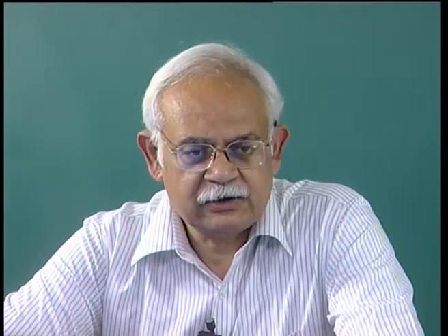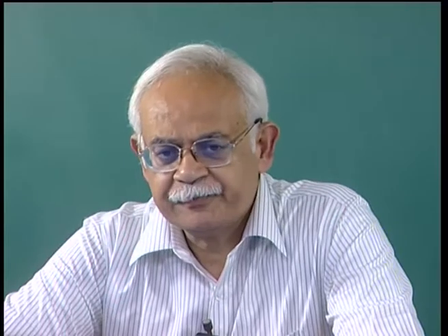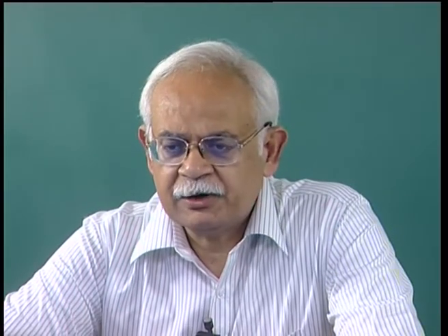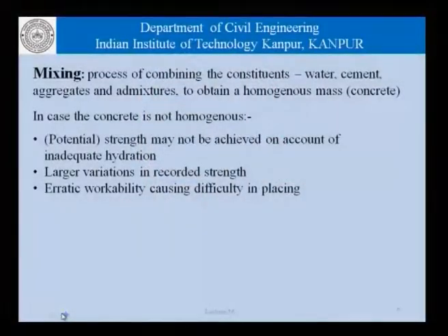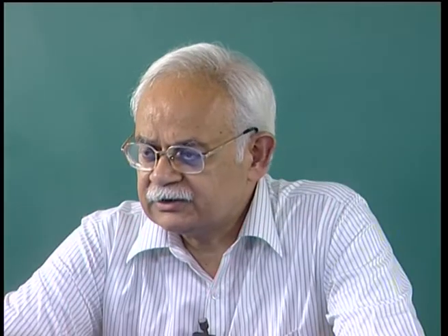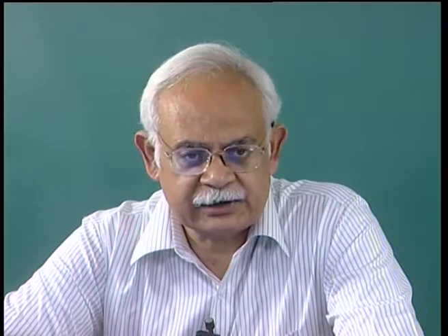If the mix is not properly mixed, even that potential strength may not be reached. We can expect larger variations in the recorded strength, because different parts of the concrete will have different ingredients, and therefore different strengths. This gives rise to a greater variation in the compressive strength of the cubes, and also a difference in the quality of concrete actually used in the construction.